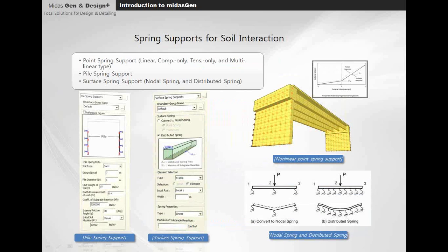Now, coming to the soil interaction. This is very important when it comes to the basic footing and the foundation analysis. We can model soil as multilinear springs to take care of the soil stiffness, and the non-linear characteristics of the spring over the pile height are automatically calculated. So, when you get the displacement, you can easily calculate the forces and the stresses developing.